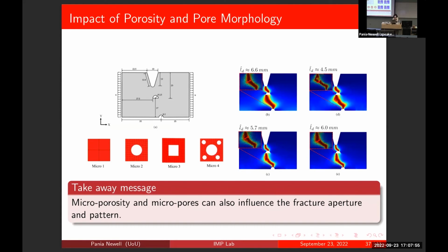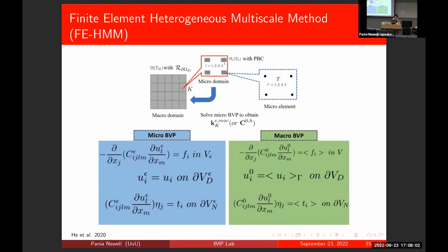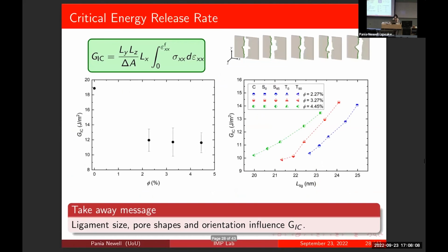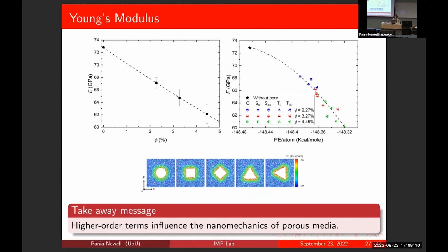These images that they have, we have another finite element model, right? So it's not molecular scale. However, what you ask, we recently, and it's not part of this presentation, used molecular dynamics simulations to inform our fracture model, as a phase field. So we didn't do homogenization. We extract these properties and put them in our fracture model, because fracture needs some input parameters for our phase field. So we informed it. We didn't couple it, and we didn't do any homogenization.